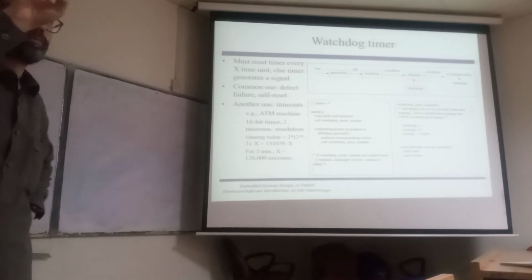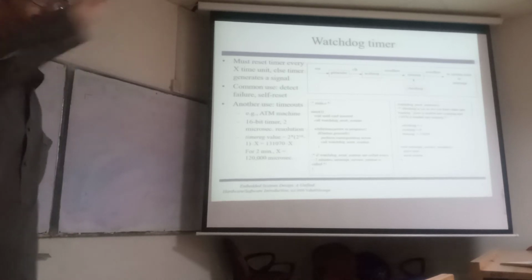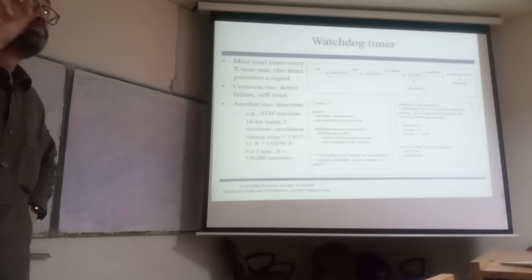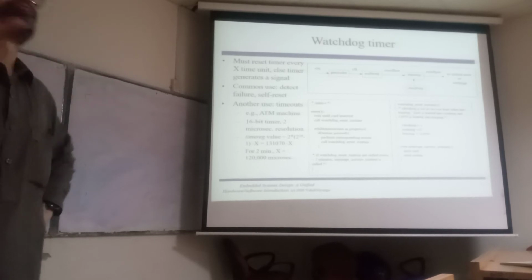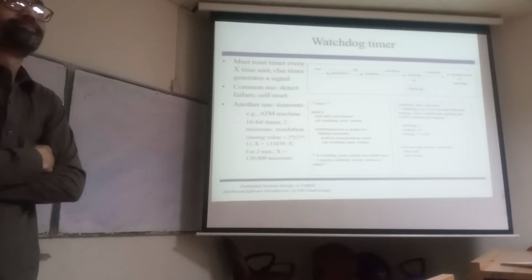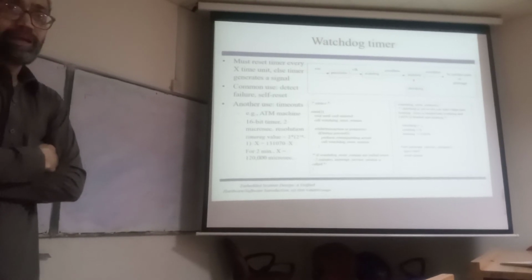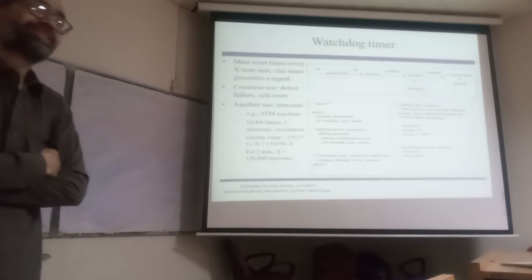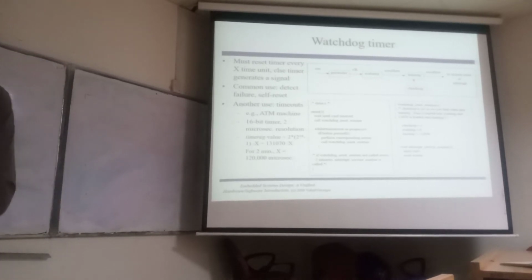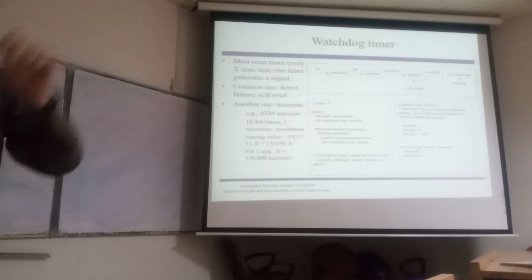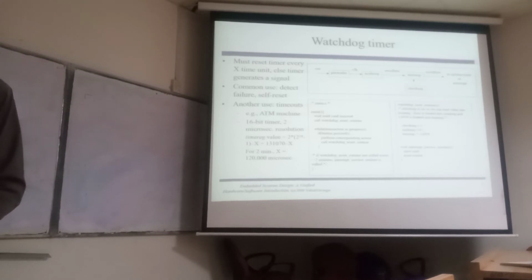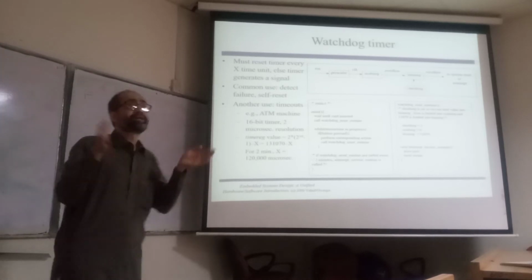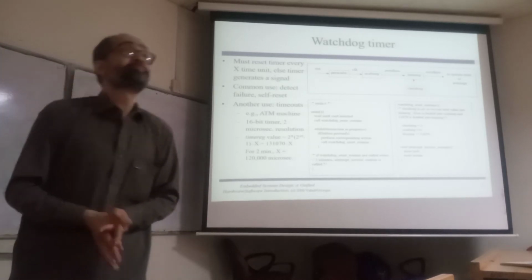Now there are two scenarios. When the user inserts his card and does not press anything for 2 or 3 minutes, what will happen? There is a watchdog timer inside. It's expecting some input and it resets the system each and every time. So it's used to avoid any unanticipated events, unpredictable events.